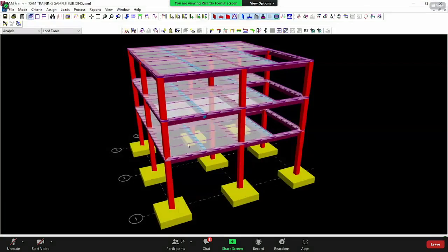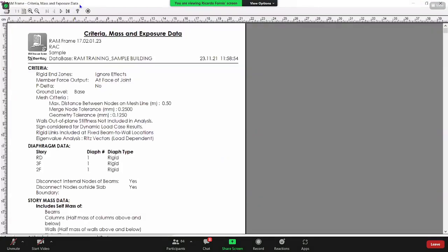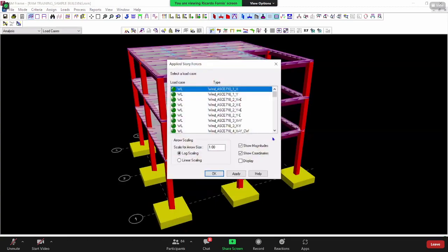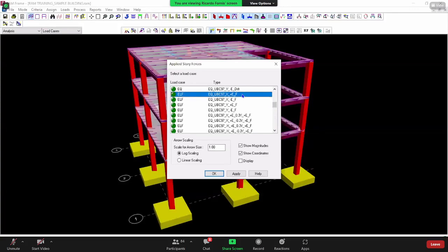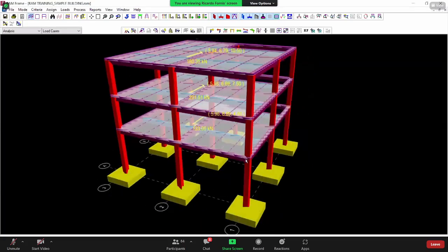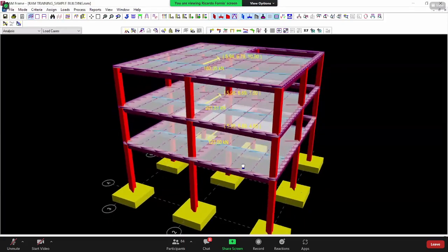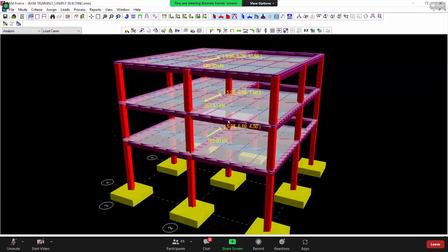So if we go to the building structure, building story shear, applied story forces, it will look like this. If you model this in the 3D model, your seismic force is applied, although the value here is different, no? I think it doesn't consider the different period.